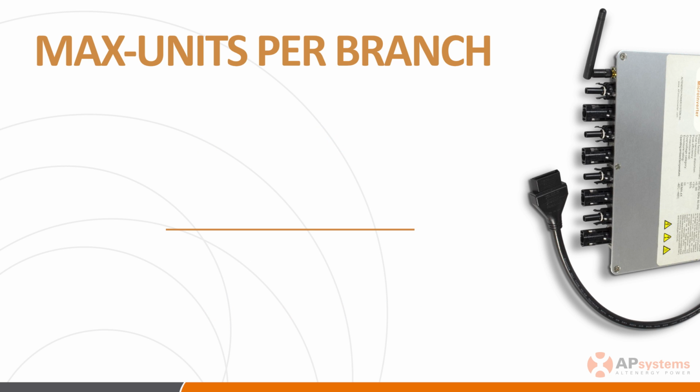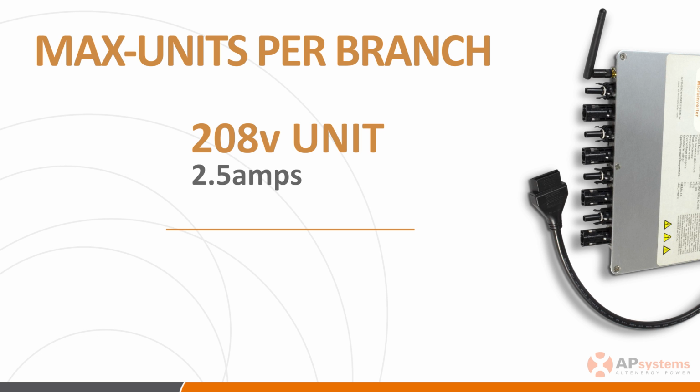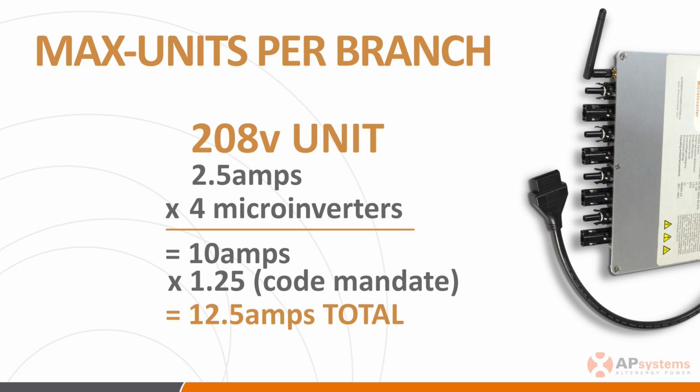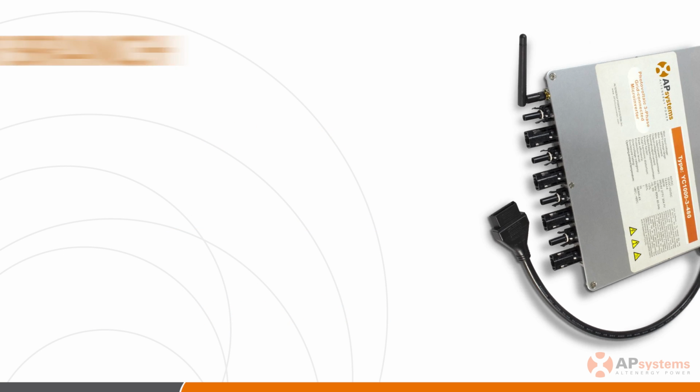Using the same approach, the 208 volt inverters are spec'd at 2.5 amps per phase. Multiplying the 2.5 amps times 4 equals 10 amps, and then multiplying that result by the code-mandated 1.25 equals 12.5 amps per phase, which again is under the 15 amp circuit sizing.